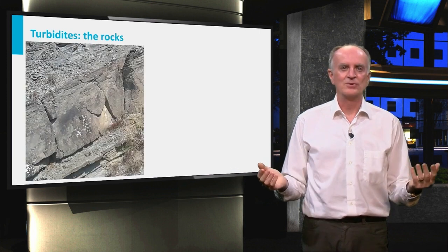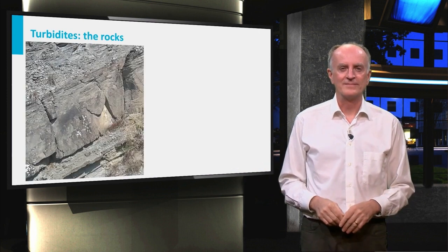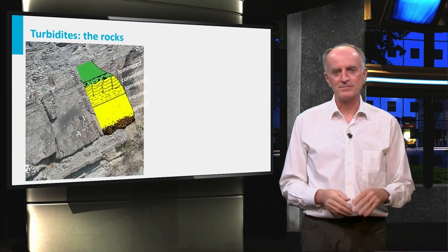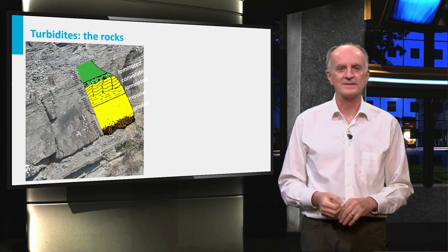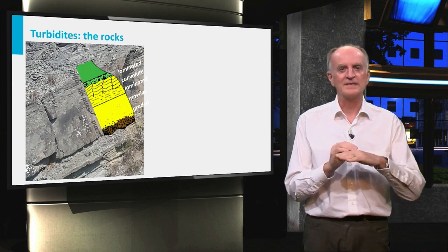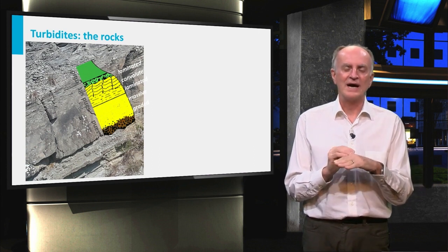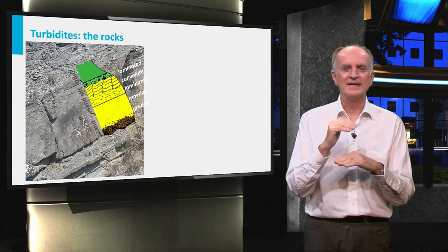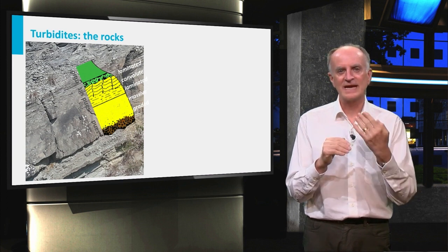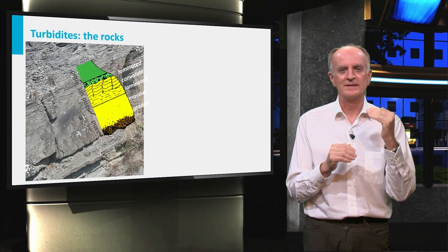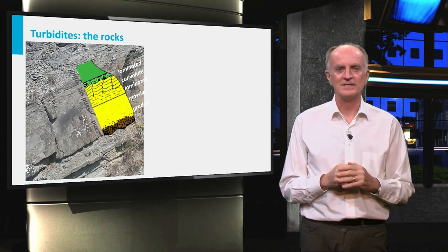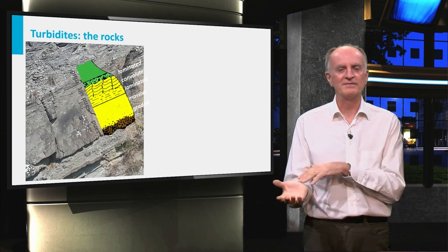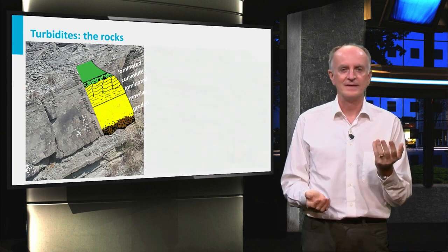And now, let us look at what turbidite deposits look like. Sedimentary layers deposited by turbidity currents have a typical organization called Bouma sequence. This includes gravel at the bottom, followed upward by massive beds, by laminated and convolute sands, eventually capped by the hemipelagic mud. These muds represent the background sedimentation deposited between one catastrophic event and the other.